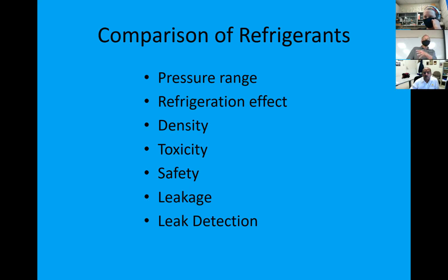Their problem was, as I mentioned before, you just don't switch from one refrigerant to the other because of, you're probably guessing it, the refrigeration, like how much refrigeration do you get per pound and so forth. You're thinking, yeah, with ammonia you can have a little bitty pipe and that ammonia does a lot of cooling for you.